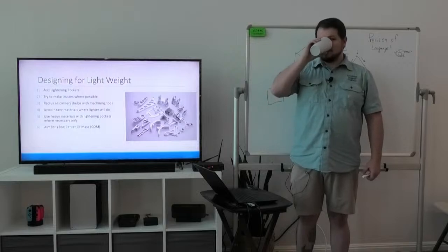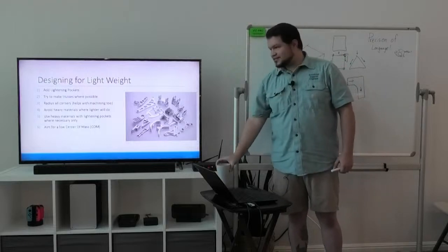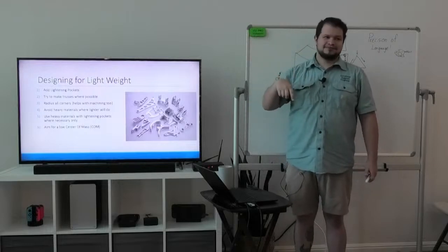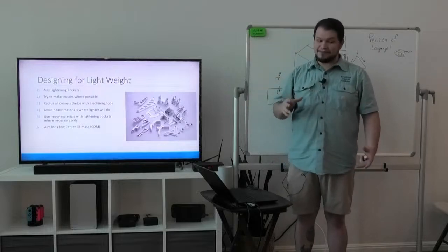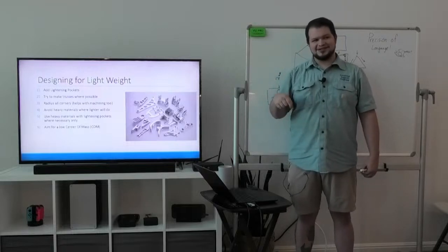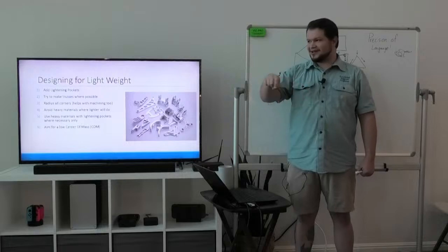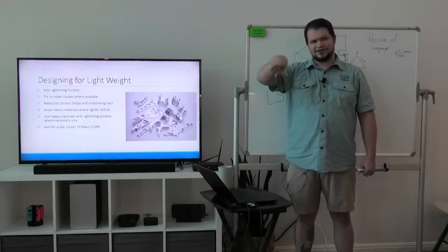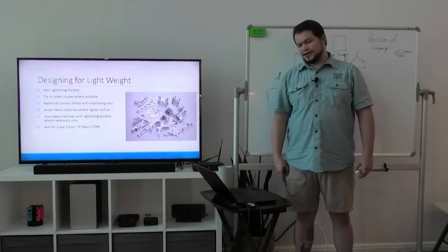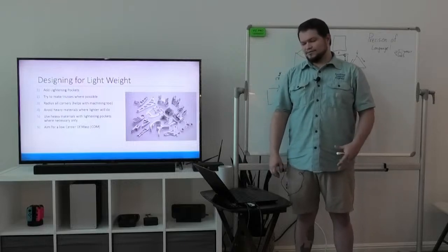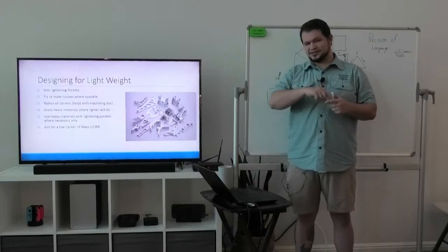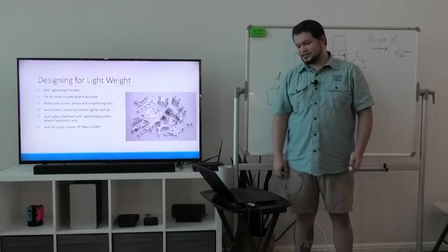It's hard to get square corners in machining. It is. If you're cutting something with an end mill, it is typically round. Not always, but for 90+% of cases, it's going to be round. So when I cut something with a round edge and go to another point, it's going to leave a little curve there. You can make that curve really small sometimes, but most times you want to cut fast, so you want to use a big end mill, which means a big radius. So leave as big a radius as you can.